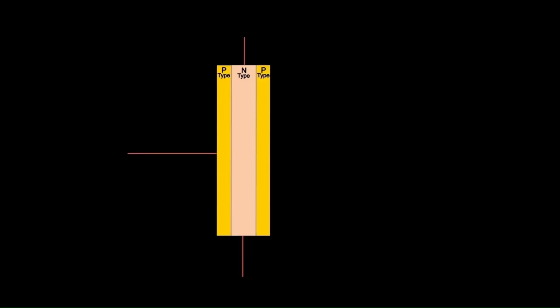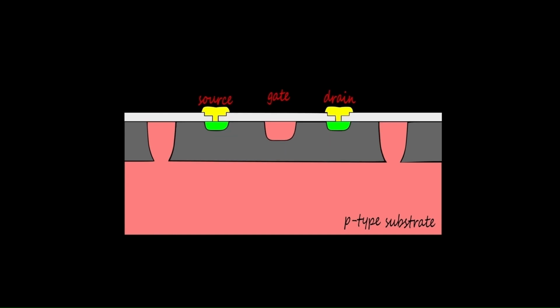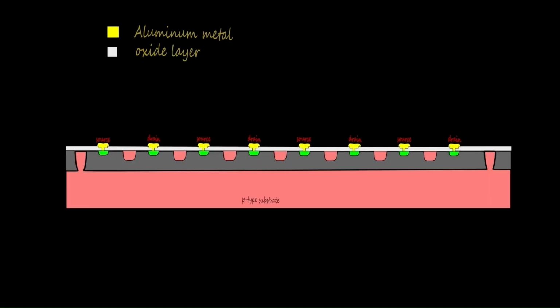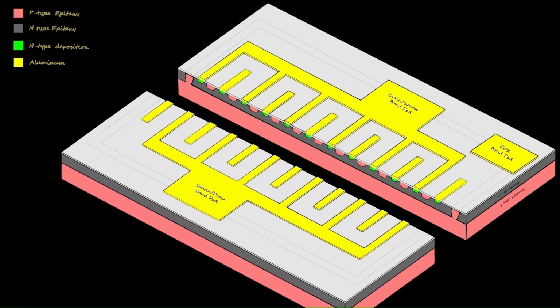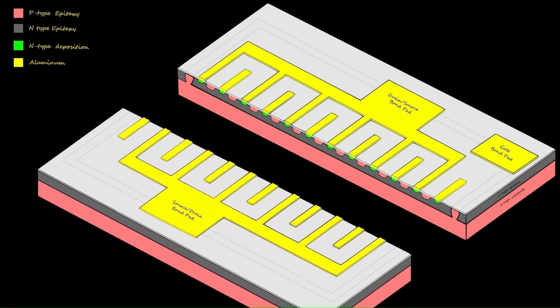So instead of a straight channel like the simple model, the planar JFET will have a U-shaped channel. The current will flow from the drain connection at the top, down through the channel under the gate, and back up to the source terminal on the far side of the gate. By shaping the channel in this manner, we can now add a layer of metal fingers that allow us to connect the cells to make a single JFET. The metal fingers will interlace when viewed from the top. The fingers will run to a small pad that can be used to bond to the leads of the JFET package. This is still a simplified model.